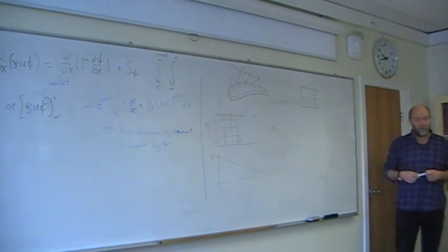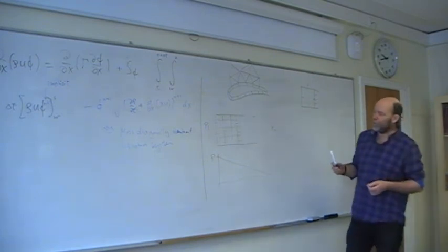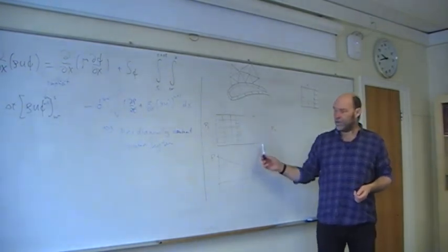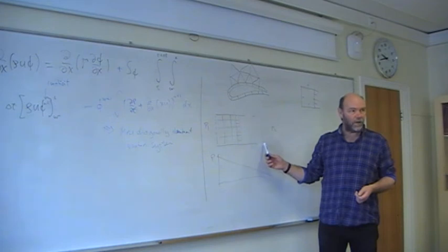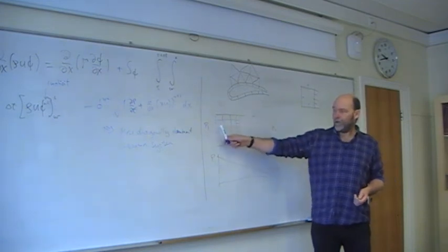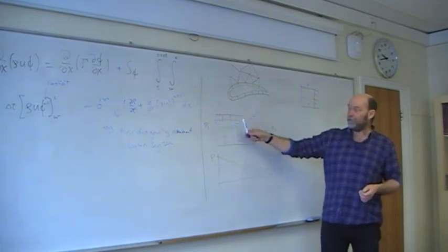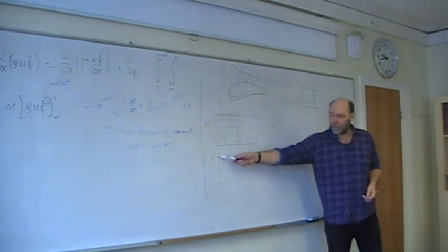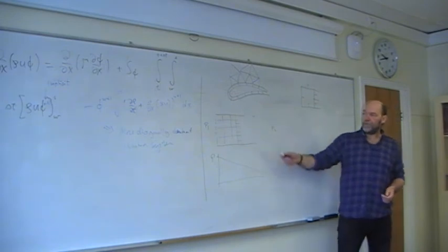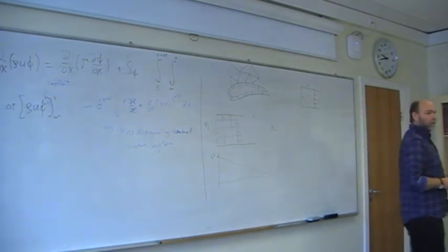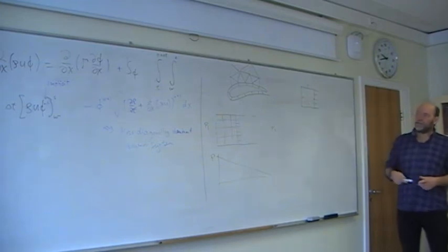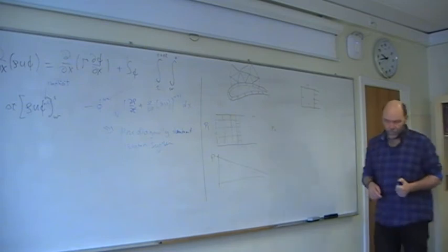And yes, they exist. But my point is, before you start using it, you do such dummy test cases like this and see what happens. A nice rectangular mesh, and all of a sudden you start to refine it or split it up or whatever, just to check that you have the correct pressure gradient between those 2 parallel plates. Very easy test to see if we can handle something like this.